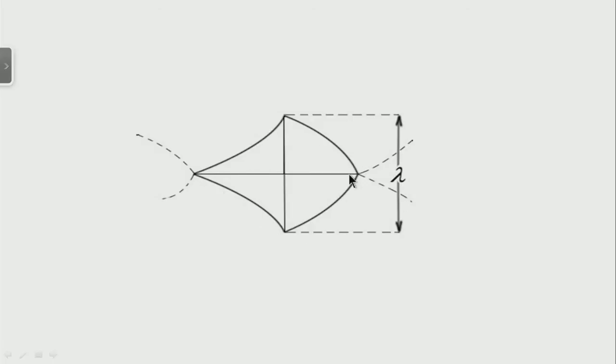It has a particular characteristic structure which is known as a detonation cell, and it is characterized by a particular dimension lambda. This cell size is characteristic of the explosive gas used, its pressure, its temperature, its physical properties, its rate of reactions. For gases which are very reactive, lambda is very small. For gases which are not that reactive, in which the mean velocity of detonation is slower, the value of lambda could be large, and there is sizable variation in lambda.